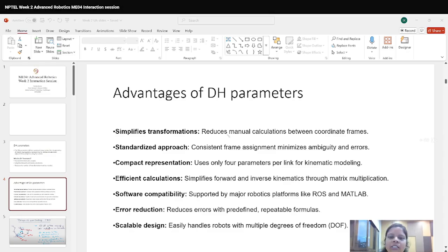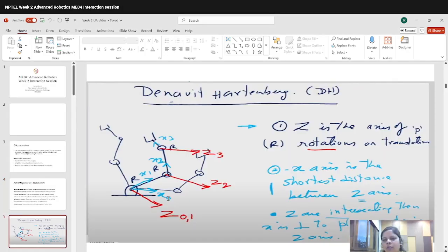Okay, so moving on to the first slide. What you see, we are basically concerned about 4 parameters over here. Okay. So what do we actually do? Let's say this is a revolute joint, this is a revolute joint, this is a revolute joint and this is just the end effector. For this revolute joint, this is called the base, right? The base is something which is not rotating and it is fixed. Now you can place your first link also there.